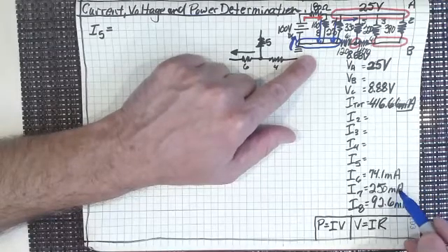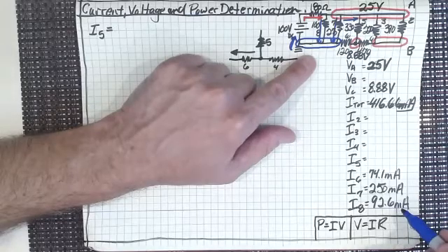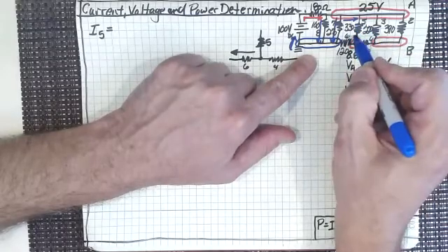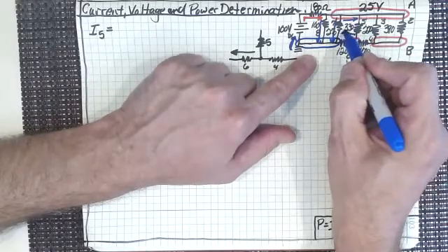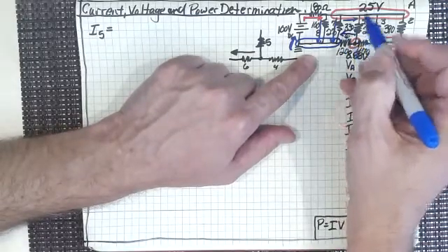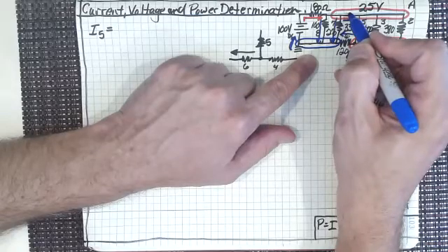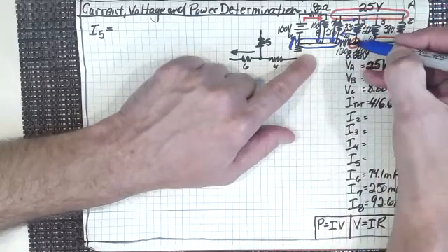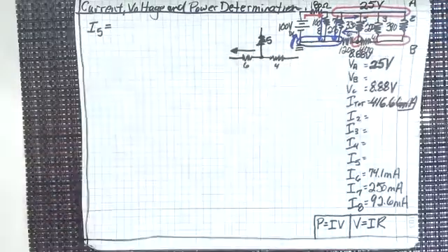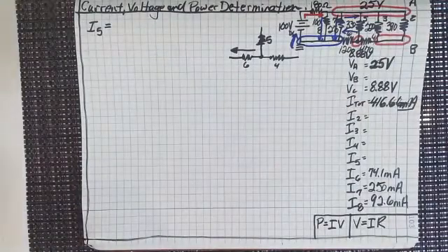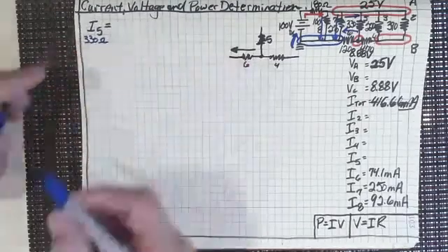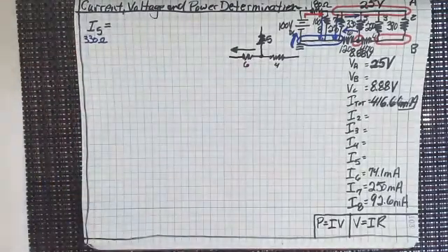So let's get back to this. We know that those two currents have come out of there. We know that the only current that's left to go in there is the same current that we figured out is coming in from resistor 6. So we know what this current is up here. We also know what the voltage differential is across this resistor, right? Resistor 5 or the 330 ohms. Let's just write that underneath. 330 ohm resistor, I sub 5. That's what we want to find out.